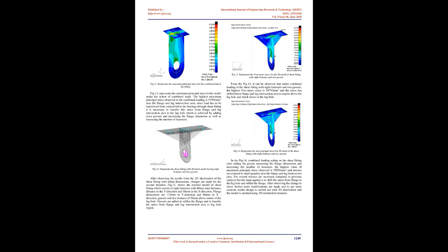The calculation of lug under oblique loading condition is as calculated below. Rfult equals 1 over (RFa to the power 1.6 plus RFtr to the power 1.6) to the power 0.625 equals 1.637, equation 10. After the calculation of reserve factors for different loading conditions, it can be observed that RF of tension failure condition as well as shear bearing failure condition is critical.